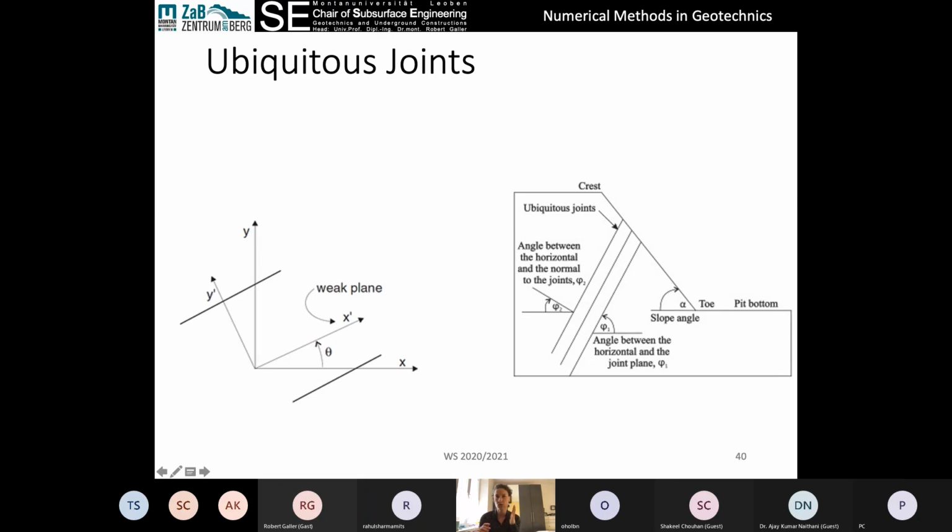So there are no discrete joints. Each element is solved twice, for the continuum part and at a certain angle. And what we will then see is little notations of failure throughout the elements. And this won't necessarily lead to shear displacements along a joint because there's no discrete joint. It's only just a test. It's a constitutive model test at a certain angle.